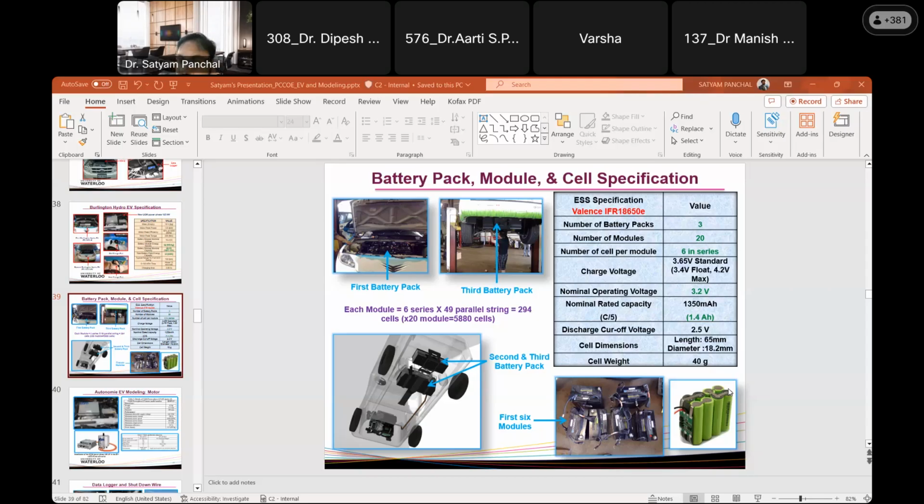Since you raised this point, 5 hot topics for industry or even for battery are: first one is the secondary use of battery, means recycling. Second one is the thermal runaway, means puncture of the battery. Third one is the thermal management. Fourth one is the aging, and fifth one is the fast charging. So fast charging is one of the hot topics right now for the battery.